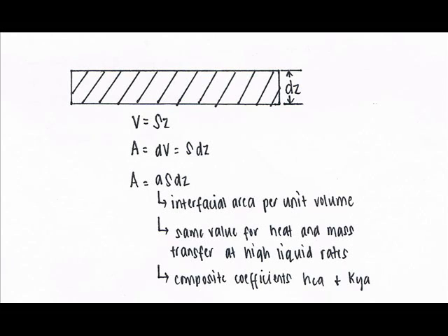For both heat transfer due to convection and heat transfer due to vaporization, consider a section of the cooling tower with a differential height dz. The volume of this slab, taking note that the cooling tower is empty, is equal to the cross-sectional area multiplied to the height z.